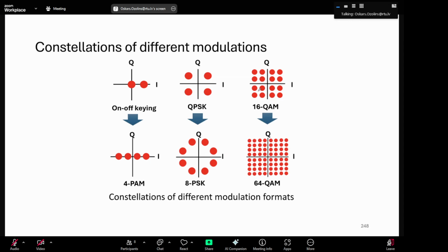And then these constellation points, I don't have a specific slide on probabilistic shaping, but I should mention it here. For example, you can choose to transmit some symbols more often and avoid transmitting others, because those are affected more by nonlinearities since more power is sent. So you start to get different effects. We are going to talk about the nonlinear capacity limit, but that will take either this week or the next lecture.